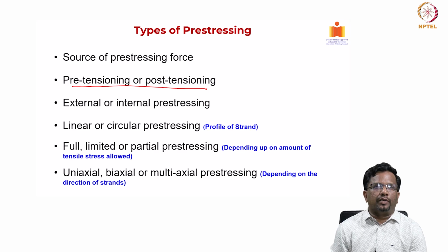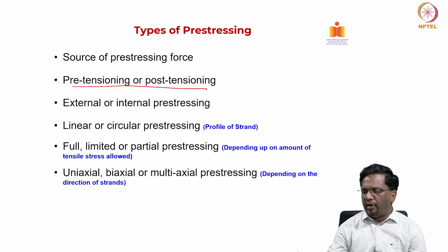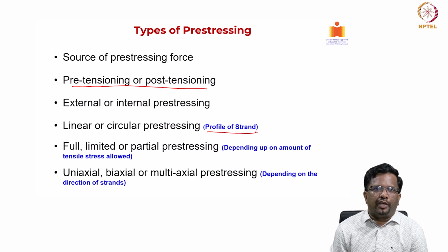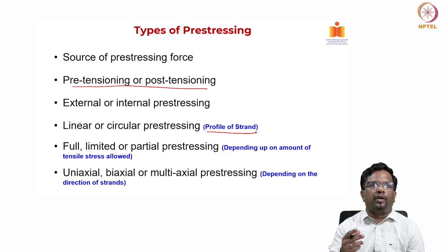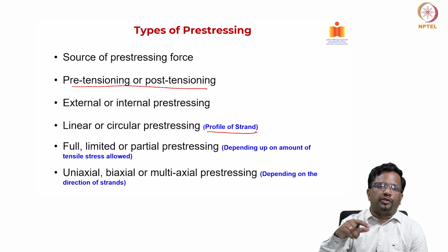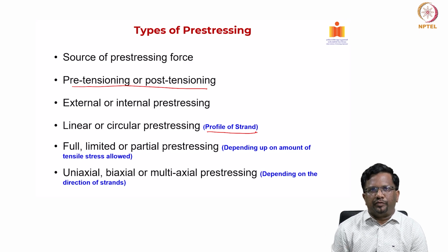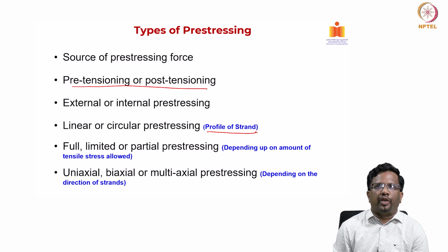Depending upon the profile of the strand, whether linear, parabolic or circular, and the type of structural element, we can classify the prestressing as linear prestressing or circular prestressing.